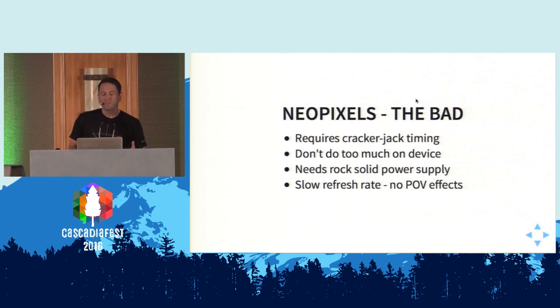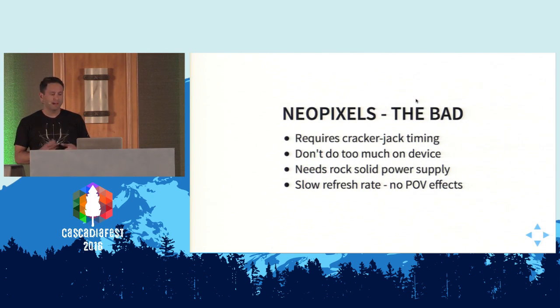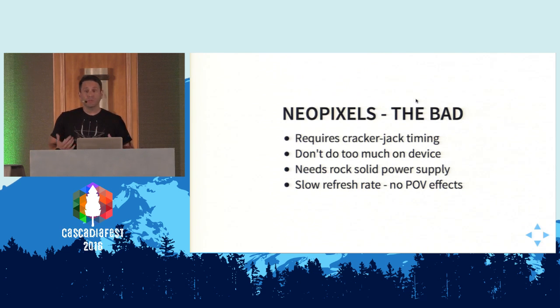But with all hardware, you have a bit of trade-offs. Because we only use that one I/O pin, timing of the signals that go to the LEDs are actually really, really critical. And so you can't do anything on the device while you're updating the LED strips. And if you're working at 30 or 60 frames per second, that doesn't give you a lot of time to do anything else. And if you have hardware interrupts, you have to actually turn them off during the time that you're actually updating the LEDs. The other thing about the NeoPixels is that they're actually a little bit susceptible to power fluctuation, so the reliability goes down if your power supply isn't super rock solid.